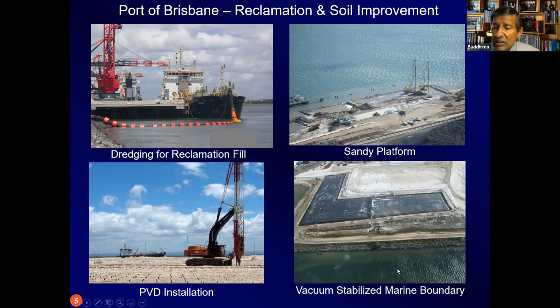And as a result, in order to control this lateral movement, obviously, the best solution was to apply the vacuum preloading, because vacuum preloading will decrease the lateral movement because of the isotropic compression that is inwards when you apply the vacuum pressure. I will explain this a little bit later, but to repeat, the most important aspect is that vacuum preloading can control effectively the outward lateral movement.